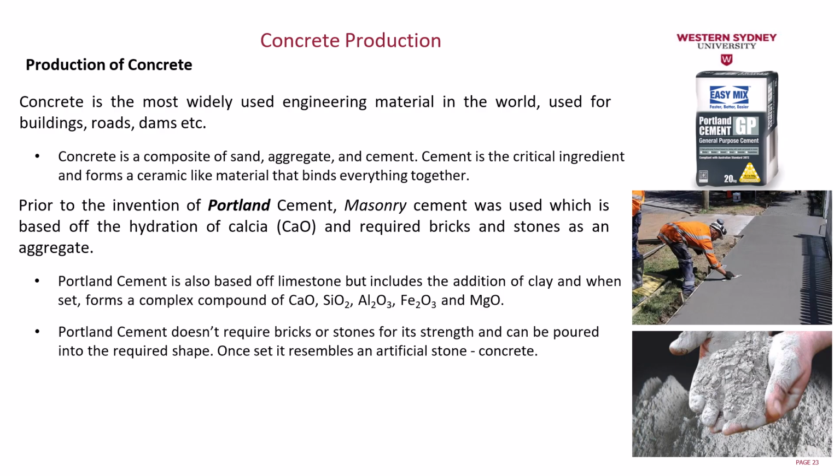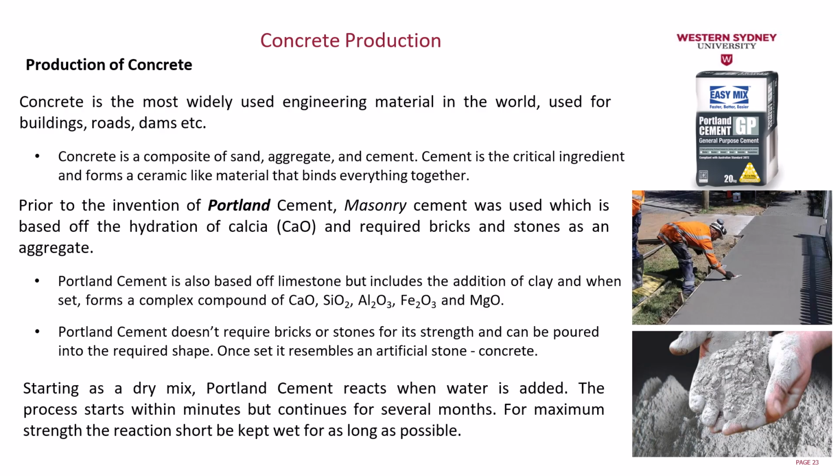Portland cement does not require bricks or stones for its strength and can be poured into a required shape, and once set it resembles an artificial stone, which is known as concrete. Starting as a dry mix, Portland cement reacts when water is added, and the process starts within minutes but continues for several months. For maximum strength, the reaction should be kept wet as long as possible.